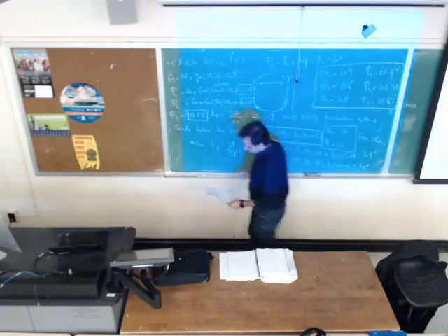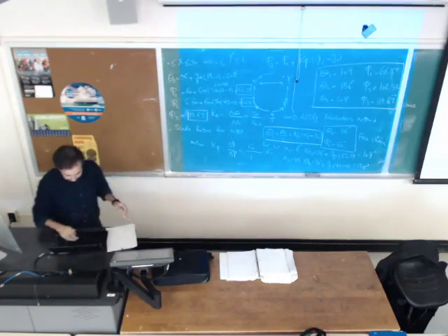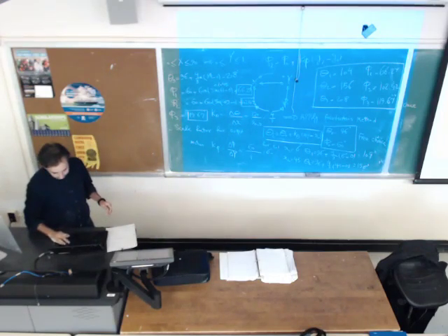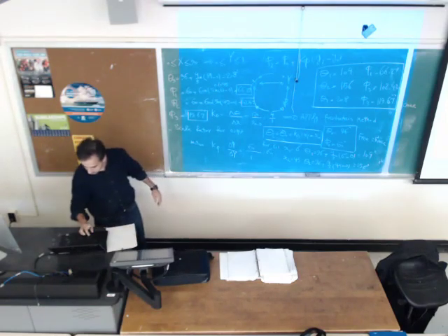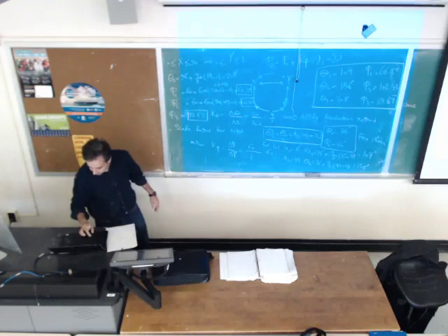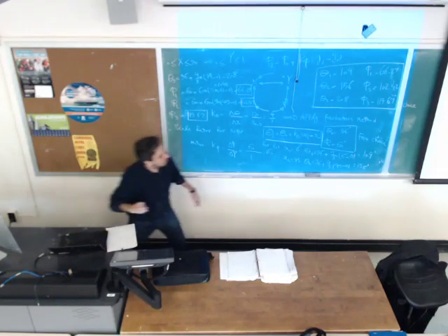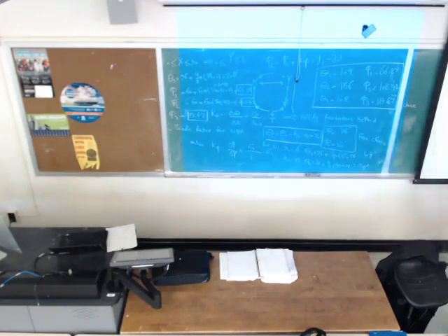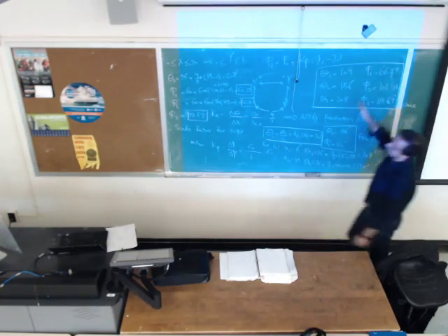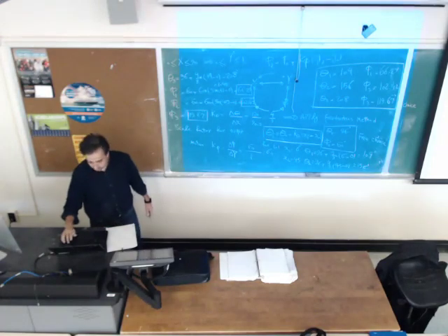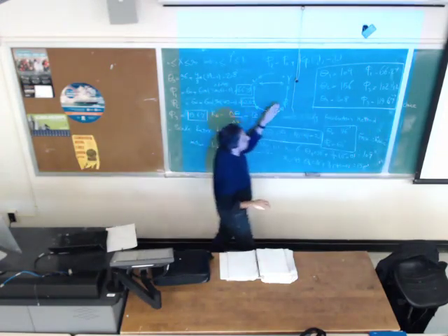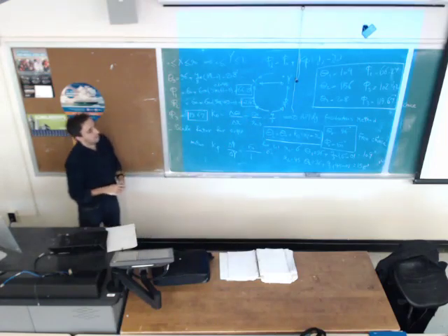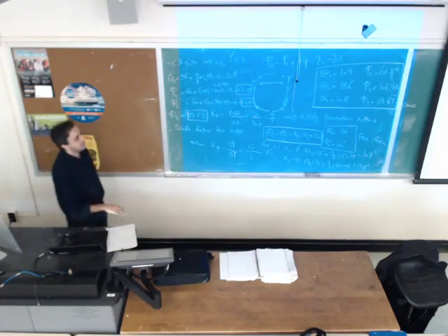So now we are back to this problem. We are given theta 1, theta 2, theta 3, phi1, phi2, phi3. With this set of data, set up these equations in matrix form, find K1, K2, K3, and design or synthesize the mechanism.